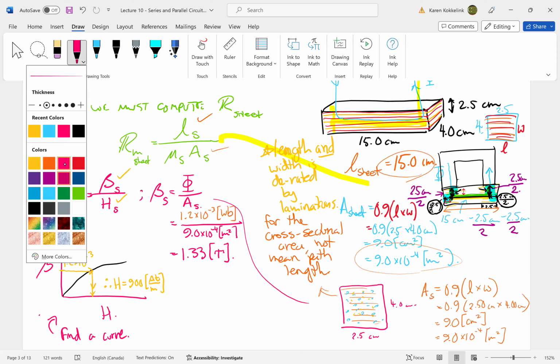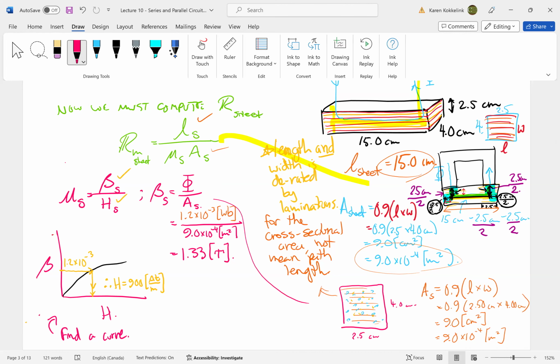So now I have my density and I have my magnetic field strength. I can calculate my permeability. At this point, I've been working so long on this question, I forget why I need my permeability. But let's continue. I have 1.33 Tesla in the numerator over 900 amp turns per meter, which gives me a permeability, which means how accepting this cross section is of making this flux.